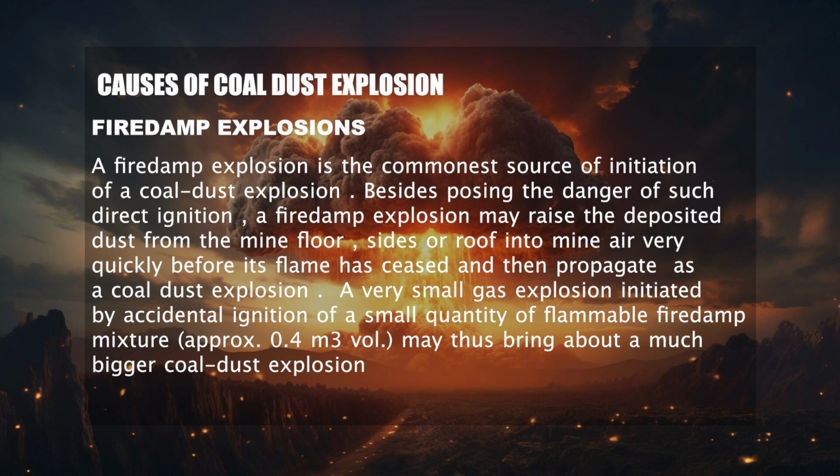A very small gas explosion initiated by accidental ignition of a small quantity of flammable fire damp mixture, approximately 0.4 meter cube in volume, may thus bring about a much bigger coal dust explosion. So, for the occurrence of coal dust explosion, fire damp explosion is a major contributing factor.